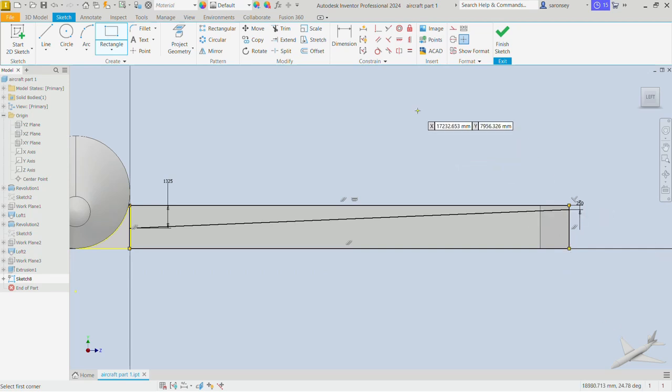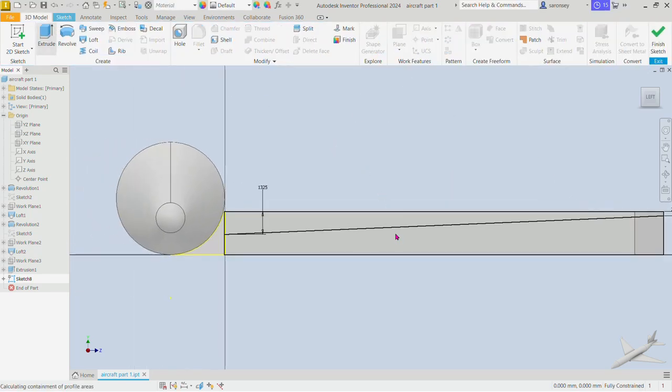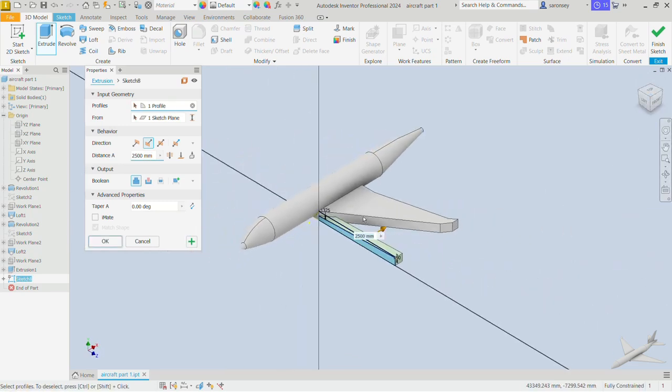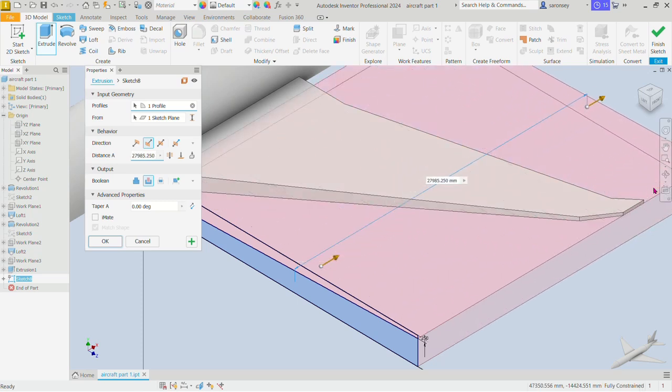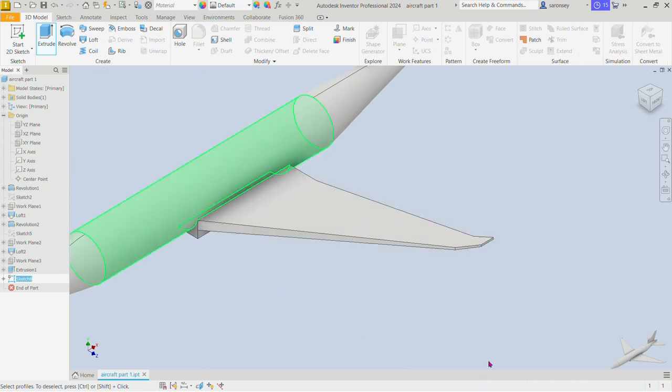at the corners. Now we can right click and OK. 3D extrude. We want to extrude this very part. Let me get a good view of this. Okay, but the boolean is going to be a cut. I will define that cut with this arrow, this very one. So just touch on it and drag it all the way across this wing, and then we can OK.